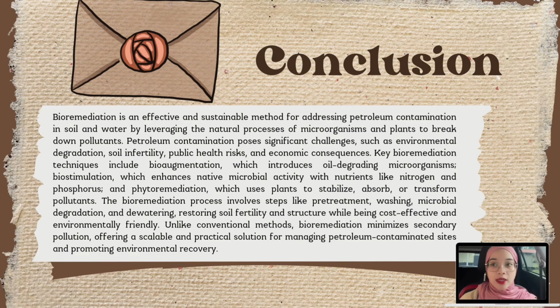Key bioremediation techniques include bioaugmentation, which introduces oil degrading microorganisms, biostimulation, which enhances native microbial activity with nutrients like nitrogen and phosphorus, and phytoremediation, which uses plants to stabilize, absorb, or transform pollutants. The bioremediation process involves steps like pre-treatment, washing, microbial degradation, and dewatering, restoring soil fertility and structure, while being cost-effective and environmentally friendly. Unlike conventional methods, bioremediation minimizes secondary pollutants, offering a scalable and practical solution for managing petroleum-contaminated sites and promoting environmental recovery.